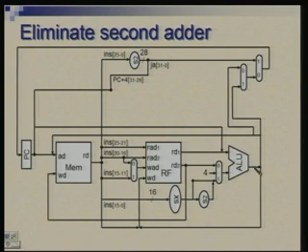What will actually happen is that although this value is a PC plus 4 value which is coming on this line, and it is meant to go to PC immediately, the other thing which is coming here after offset addition is meant to again go to PC, but this is after comparison has been done in this ALU of the two registers, and this may go, may not go.